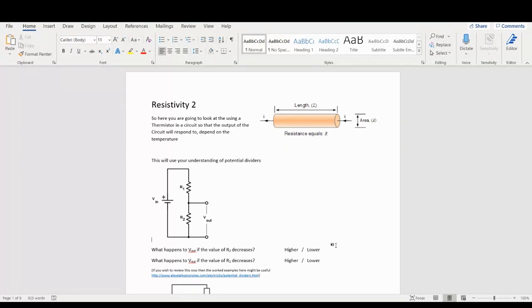Now, on the flip side, copper has a resistivity of 1.7 times 10 to the minus 8 ohm meters, which means that per meter, there's going to be about 17 nano ohms worth of resistance, which means that not much potential is going to be lost, which makes it a much better conductor. And this is where the idea comes in that everything technically is a conductor, but it all depends on how much it resists. When it resists a lot, it's not really a conductor anymore, it's actually more of an insulator. So it uses that electrical potential as heat to itself.